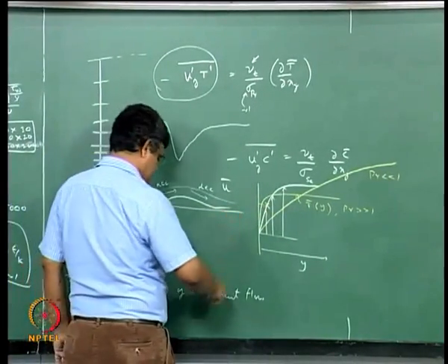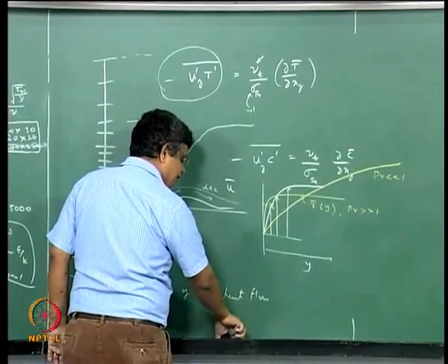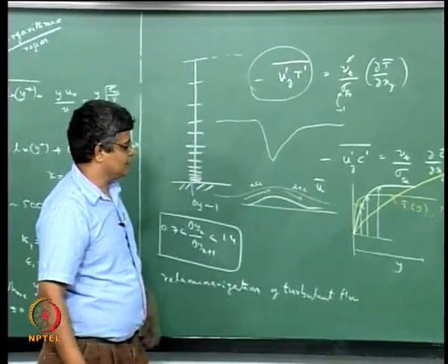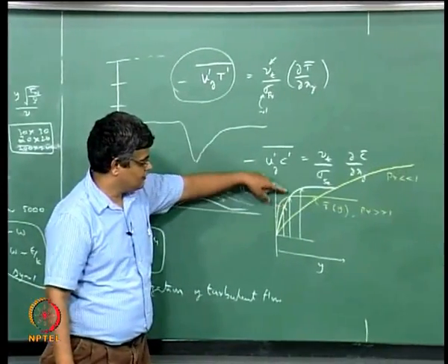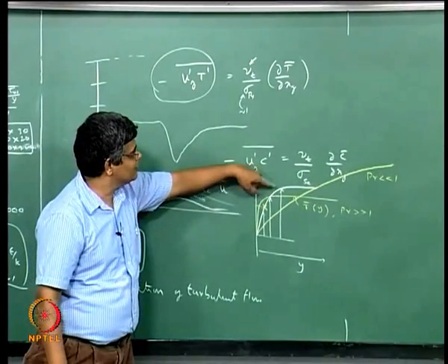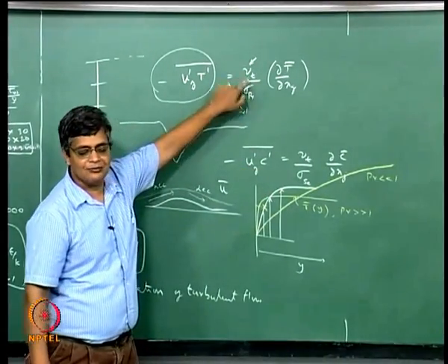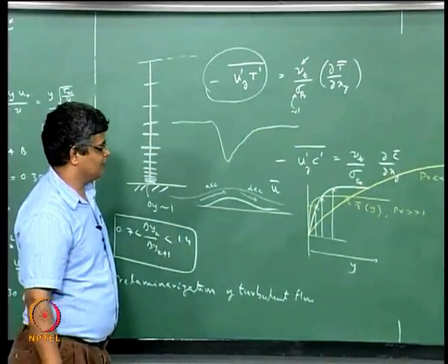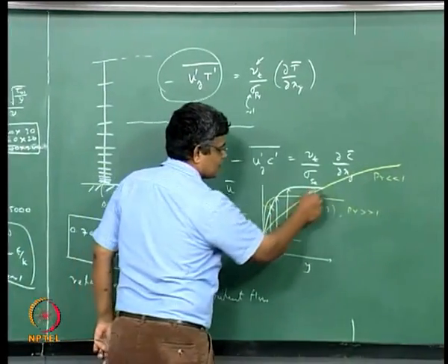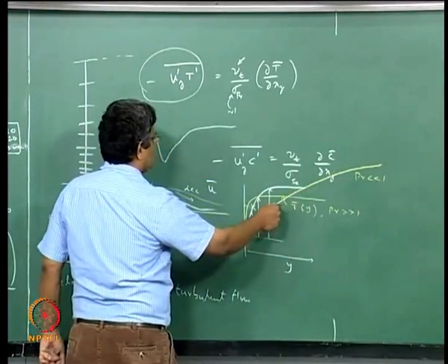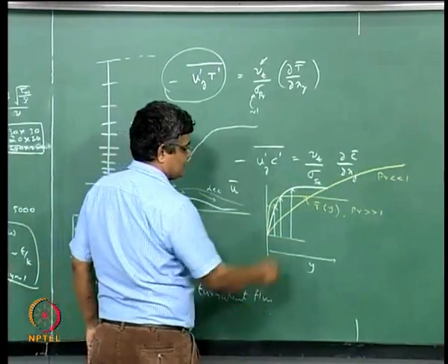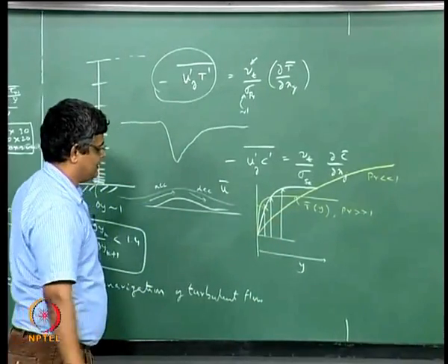So you are imposing an uncalculated turbulence profile on the heat transfer here, and there may be some discrepancy coming from that. And when you use a wall function which is a standard wall function, that again may be quite wrong here.